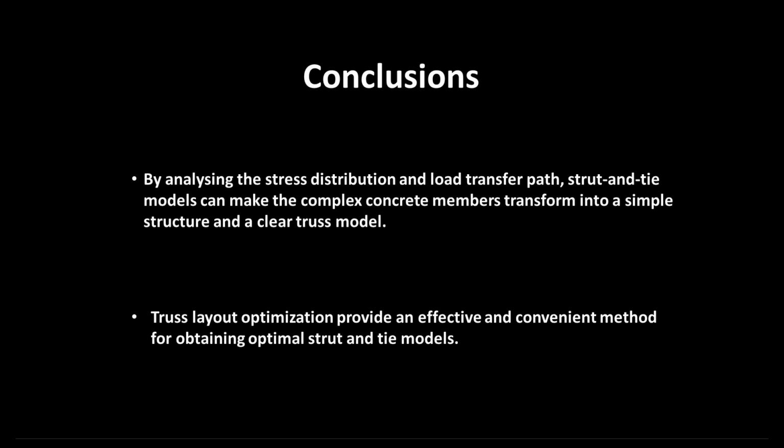From the conclusions, what did we learn? By analyzing the stress distribution and load transfer paths, strut and tie models can transform complex concrete members into a simple structure and a clear truss model. Truss layout optimization provides an effective and convenient method for obtaining optimal strut and tie models.